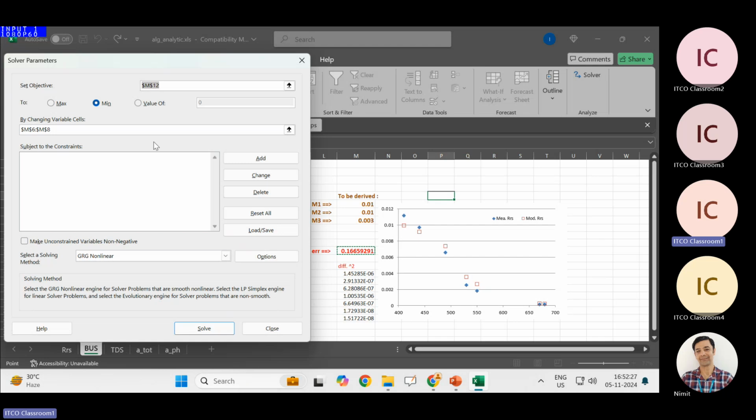So to do this automatically by computer, Solver. What you do in Solver is define the cost function, that's M12. If you know Excel, M12 is a location. That's this cell, column M, row 12. So we want to minimize the number at M12 by changing the values at M6 to M8. Here's M6, M7, M8. The computer will vary the values at these three cells with the objective of minimizing the value at M12. These are already set up. So let's click Solve. Just watch.